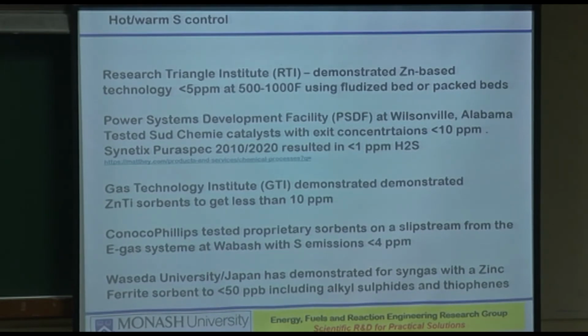Then of late, in the last 5-6 years, this is for the development of the Japanese gasification industry, and there are quite a few. Not only Mitsubishi, but Hitachi is another competitor within Japan to Mitsubishi. Then before that there was another one, and I'm trying to remember the name of it. I forgot anyway. If I remember, I will tell you later on. But Waseda University, for the R&D done for the Japanese gasification companies, demonstrated a syngas cleanup with a zinc ferrite sorbent to less than 50 parts per billion. Small scale work, but that's a massive cleanup. It's a massively efficient cleaning system.